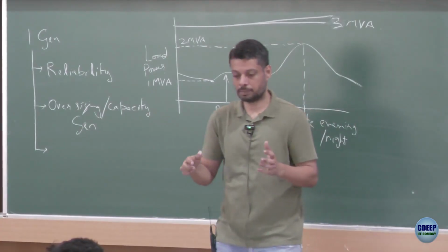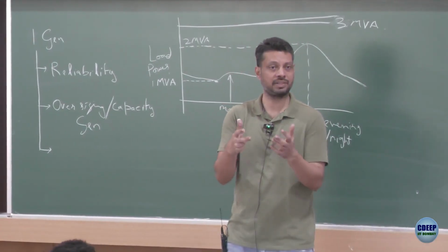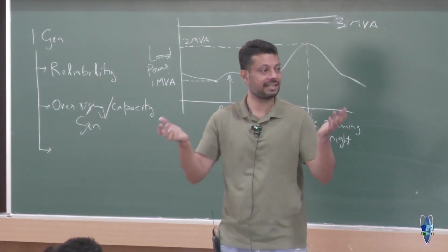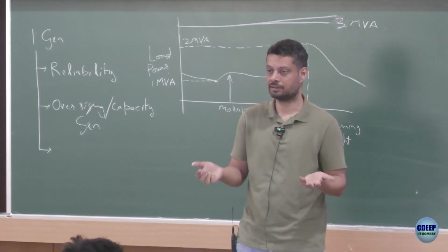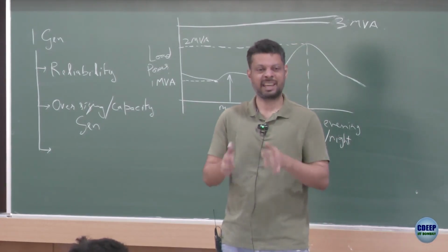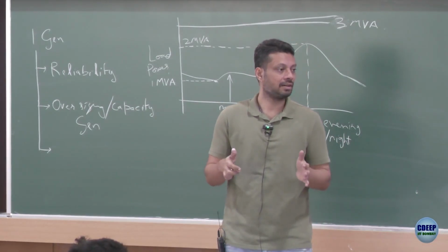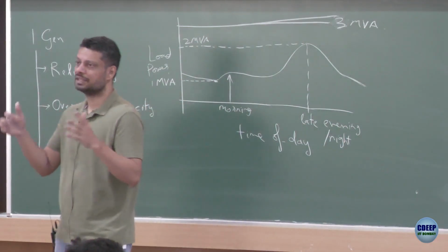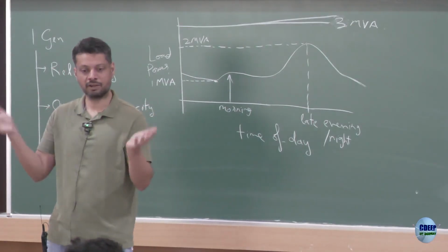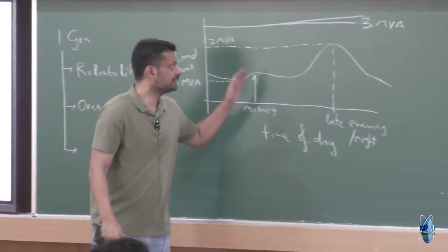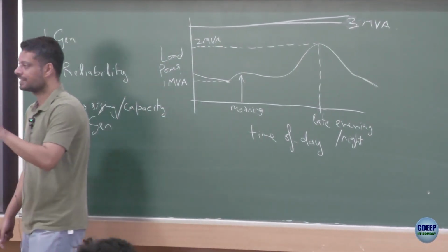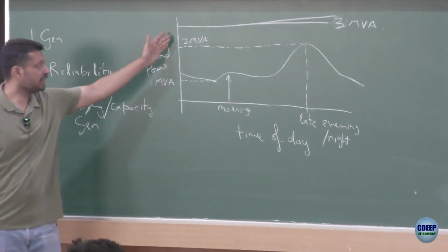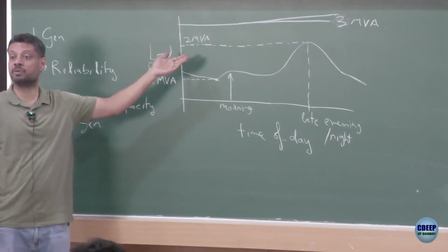For example, you make a place to burn coal, right, it will produce heat, some of it will go to the system, some of it will go out, right, it will always go out, whether you are running it at lower speed, higher speed, doesn't really matter, lower power, higher power. Again, the boiler will have some insulation, which will maintain the pressure, maintain the temperature, but there would be some heat flowing out of it always. So there is always a fixed power loss happening in these kinds of systems, and therefore they are much more inefficient if you are running at lower power as compared to higher power.